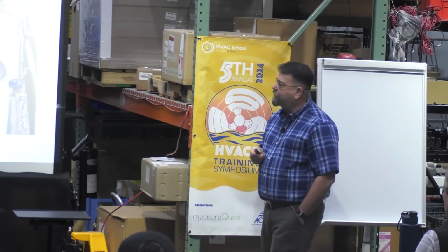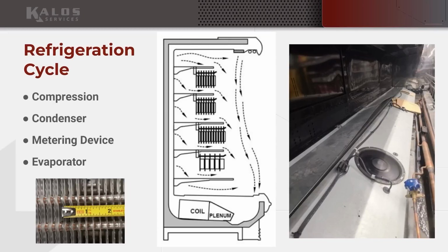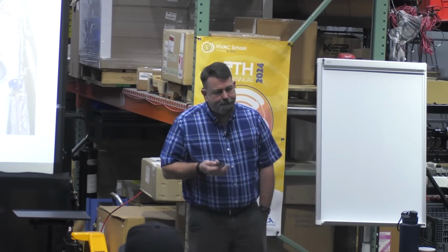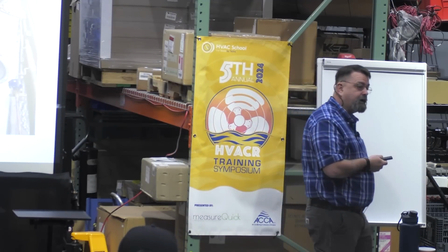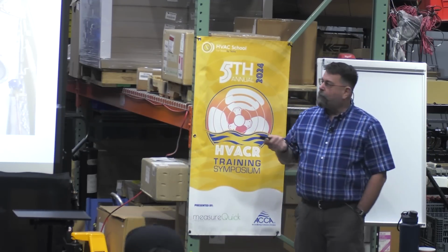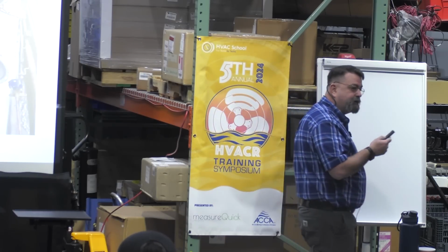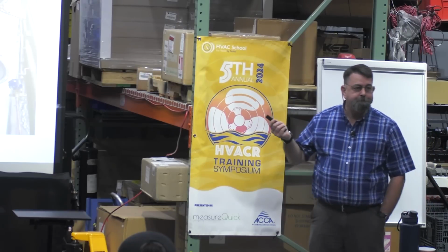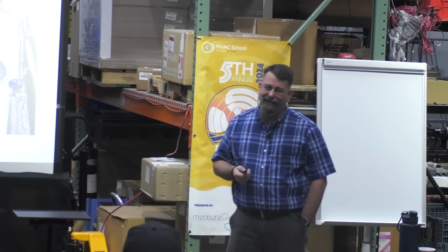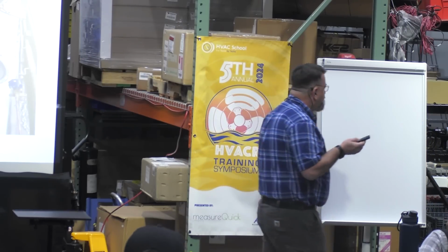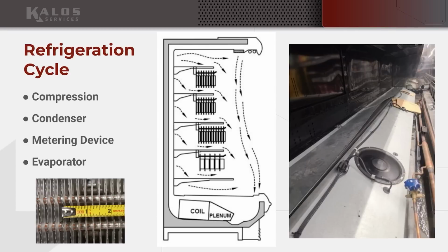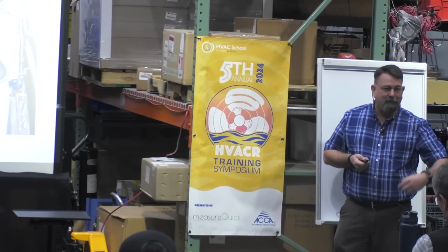The colder I get, the faster it's going to grow snow and ice, right? So when I go to medium temp, it's not uncommon to see 6, 8 fins per inch, something like that. It's kind of a standard. When I go to ice cream, I'm running at minus 25 degree evaporator, minus 15 degree supply air. That's where we run, right? All that fat and sugar didn't make it hard. It's got to be that cold. When I do that, my fins are going to go to 4, right? Wow, yeah, you can drive a truck through there, right? You start seeing some pretty big sized gaps.